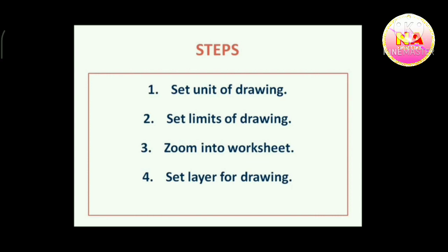Okay, that's it. Second step tells us we have to set limit of drawing. So here we set the limit of our worksheet. We set the area in which we want to work. The third step is zoom into worksheet. After setting limits of our worksheet, we zoom into it so we can have proper access to the drawing easily. Fourth step, set layer for drawing. Before starting a new drawing, we must always set a layer for it.